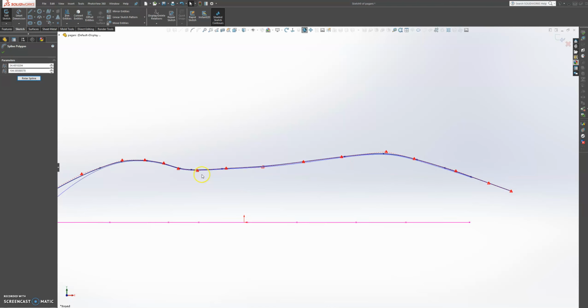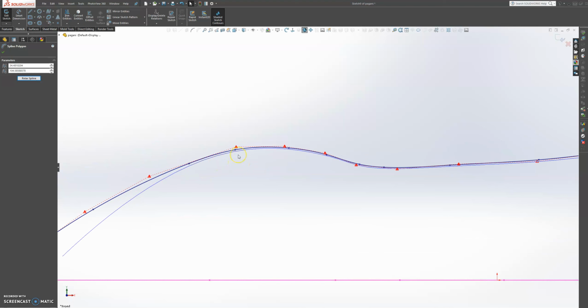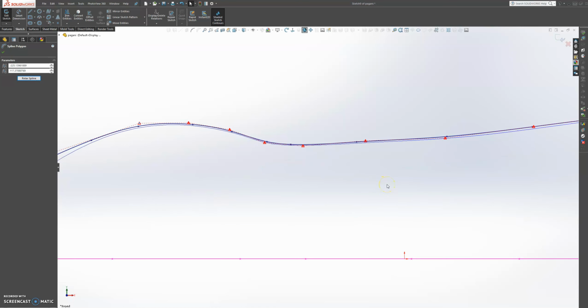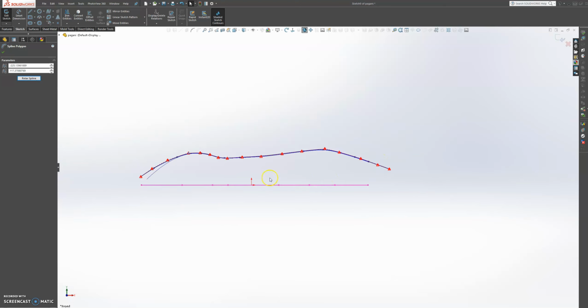Because believe me, if you let go of one spline or one surface that is not correct, it will give you a lot of hard time in the end of the design. You get trouble creating a solid, trouble knitting surfaces together, and also when it comes to rendering the design.